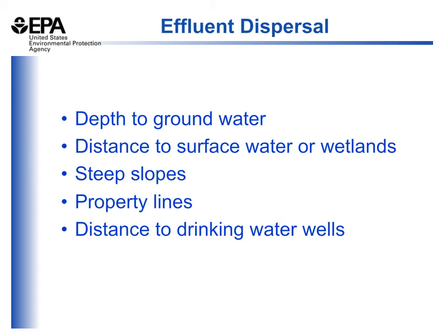It can also be determined by looking at the soil profile itself, and a qualified soil scientist is capable of reading that soil profile and estimating where maximum high groundwater might be by looking at the staining or soil mottles within the soil profile. By measuring the height of these soil mottles in the soil profile in the test pit, it's possible to estimate the depth to maximum high groundwater.